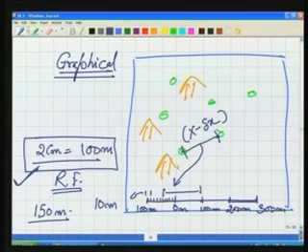Now if you use your engineer's scale in order to determine the distance between these 2 points on the ground using the map, you will measure the distance between these 2 points as x minus delta x, and apply the engineer's scale or the representative fraction on this distance.